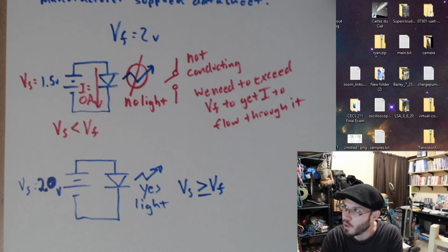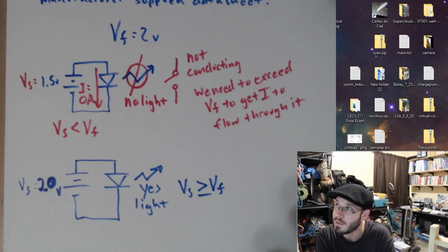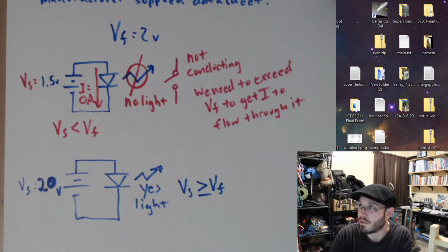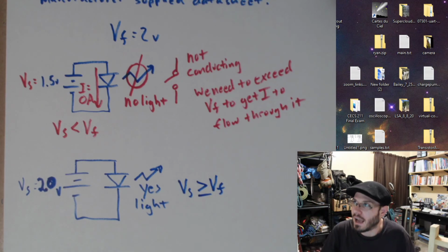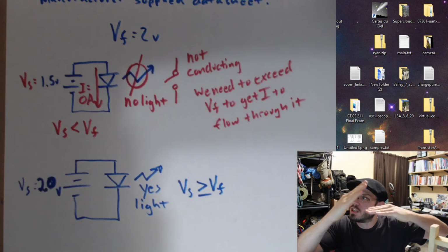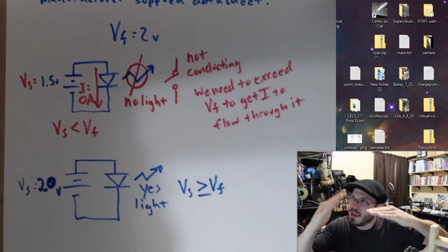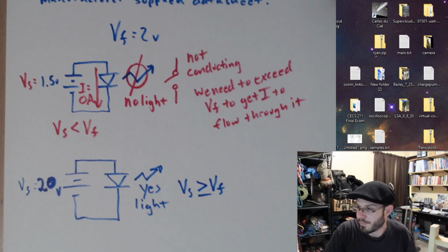Here's the deal. Forward voltage is a little bit of a floating around value. Sometimes it's 0.7, or let's just say for this diode, sometimes it would be like 1.7, 1.75, 1.85. It's not a hard line. It's not like you just equaled this value and all of a sudden it conducts. It's on a continuous range, so you have varying degrees of conduction. It's almost like the first approximation switch is partially closed, where it's allowing some current to go through it.